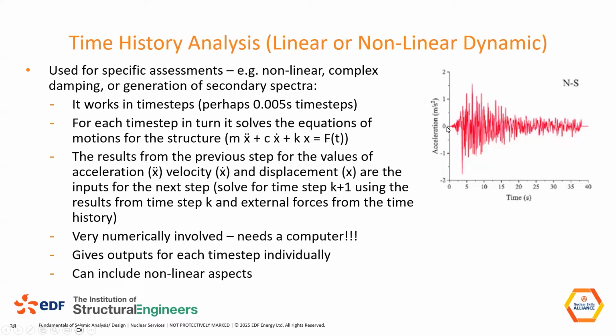So you start at 0, 0, nothing's moving, and then you have an input acceleration which causes some velocity, causes some displacement, and then for the next time step you have a variation in that acceleration, but you also have an initial velocity and you have initial displacement. So you're starting from a different position, but you resolve each time step in turn and you work your way all the way through to the end.